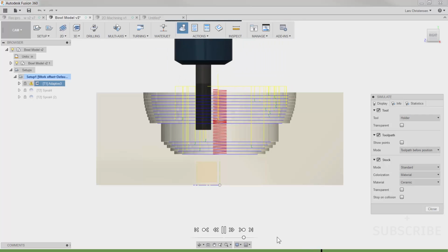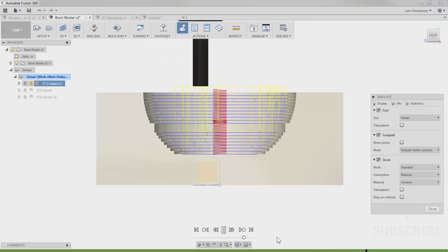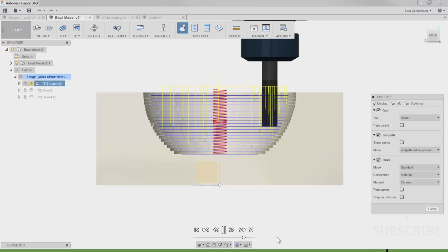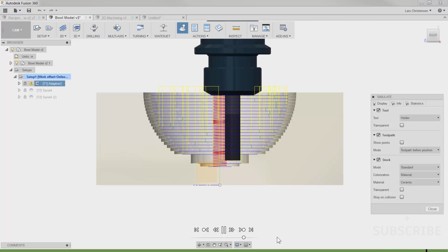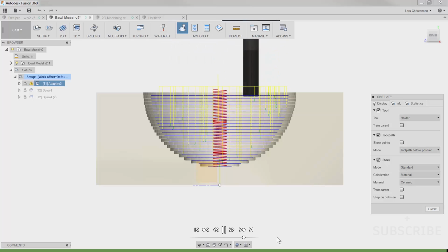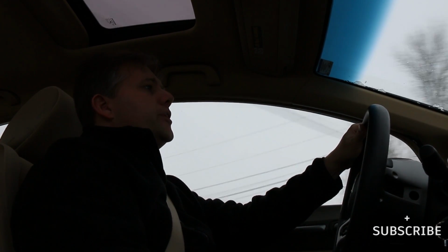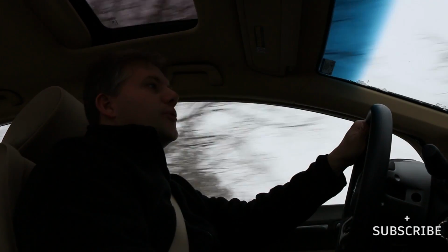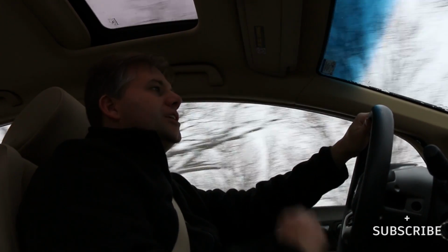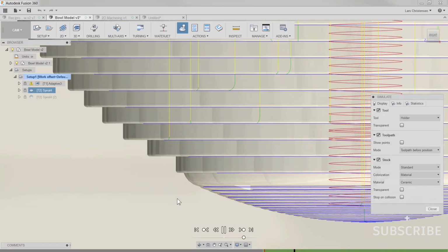Now, many times when you're machining things like this, you will actually use a roughing operation, semi-finish, and then finish, sometimes multiple semi-finishes. So after our adaptive clearing here, you will see that I'm coming in with a semi-finish operation. Really all you're doing when you do semi-finish is leaving a little bit more stock, and then you can make your step over a little bit bigger.